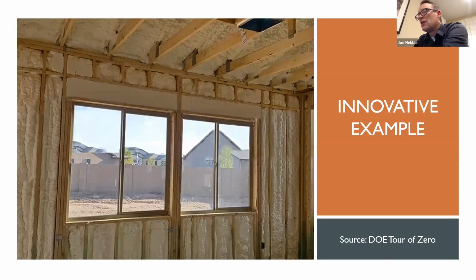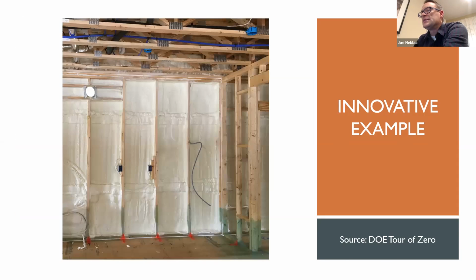This is an open cell spray foam, I believe, and I think this is climate zone 2, but in Arizona. So this is a wood framed wall, and they're using a spray foam in the cavity. This is part of a flash and bat system. So they've sprayed a small amount of closed cell foam, and then they're going to add bat insulation in the rest of that cavity.